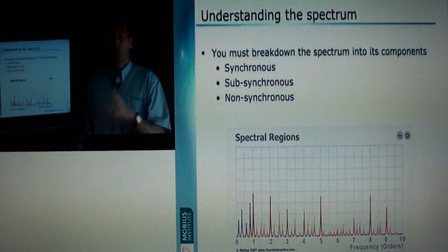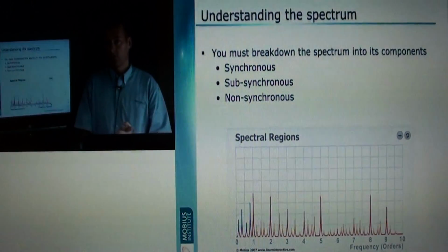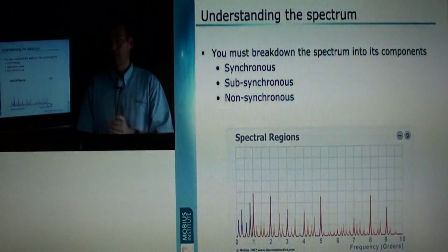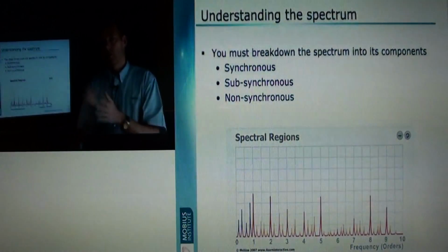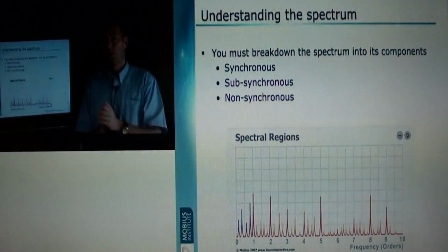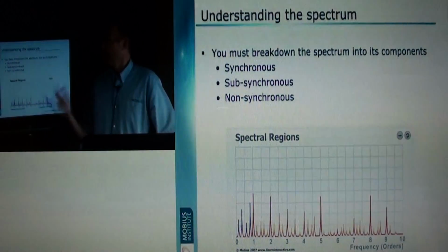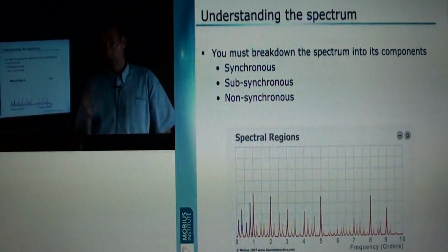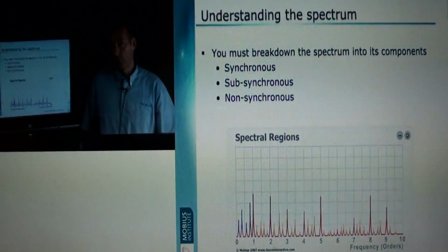Anyway, you will notice that the harmonics will only line up when you've got a non-synchronous frequency. If it was really 3x, then the second harmonic would be at 6x and the third harmonic would be at 9x instead of being 3.09, 6.18, and 9.27. They will line up that way, so you can tell. You just have to normalise it properly in the first place.